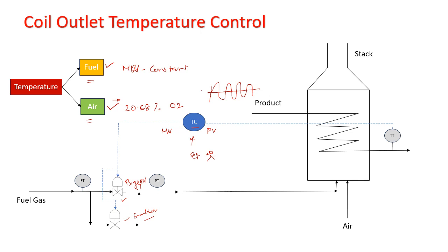Then again, you want to decrease the temperature, right? And for decreasing the temperature, what will you do? You will close the valve, right? Then again, opening and closing of the valve, and along with that, the cycling of the temperature will occur. So it will be very difficult to reach a steady state.